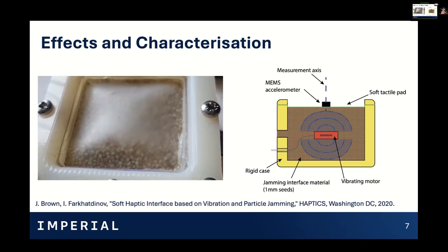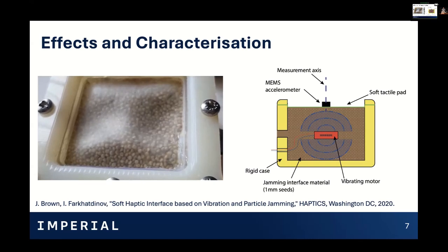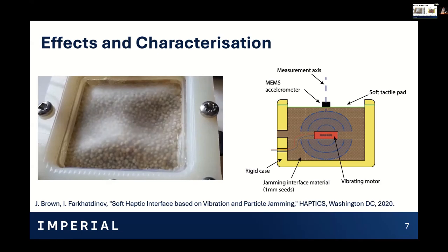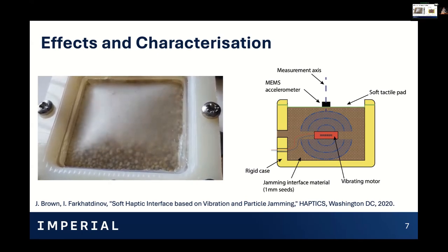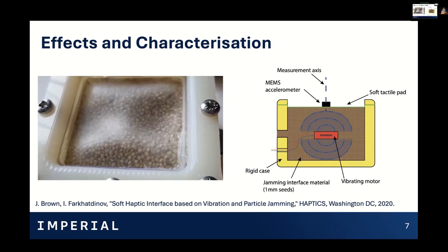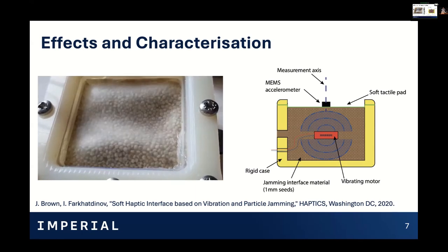And the first thing we needed to do with this technology once we designed it was to characterize it and see how do these different tactile modalities interfere with each other in an engineering sense. So to do that, we were really interested in the vibration propagation. So we just attached a small accelerometer to the top of the silicone surface to see what the vibrations did when we jammed the particles.